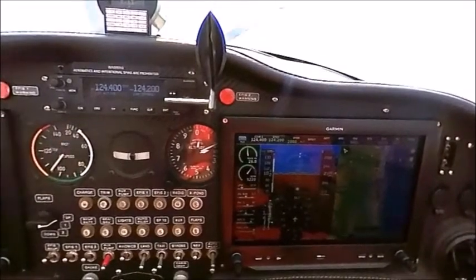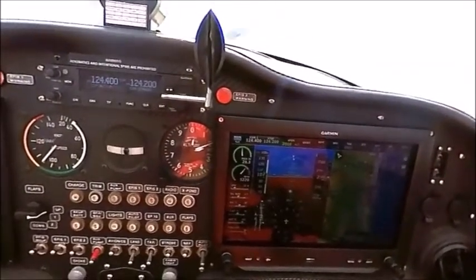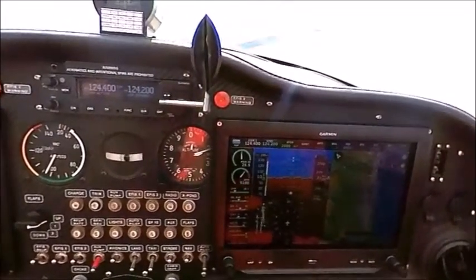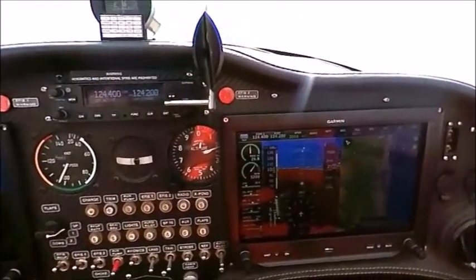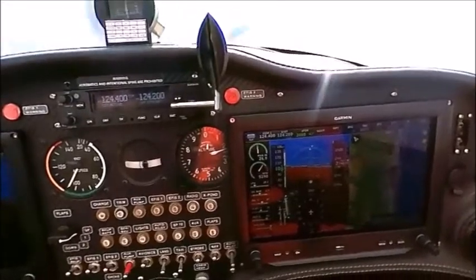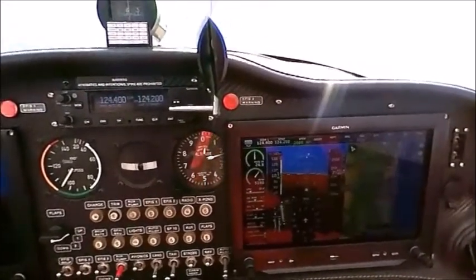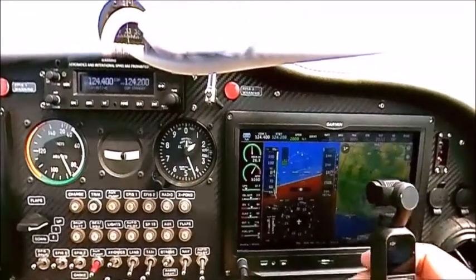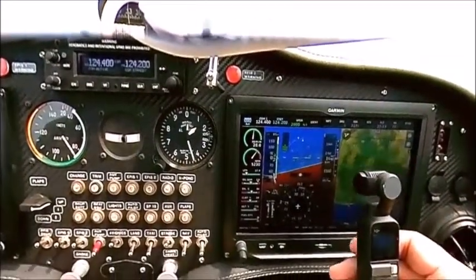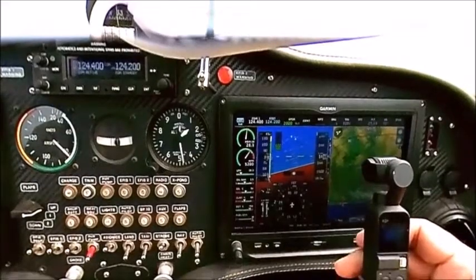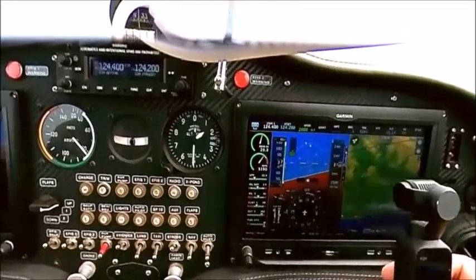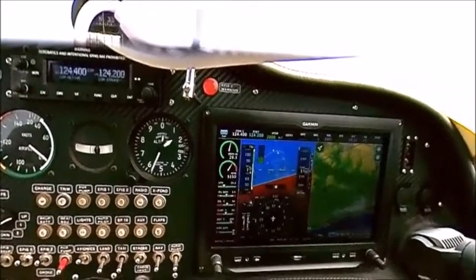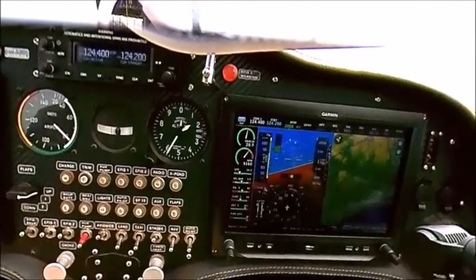Okay, so I'm going to be doing some examples. I'm showing you different air speeds. You will see over here with the analog system, it will show you we're going about 105 knots, while on a digital system, you will see that we're going at around 100 knots. So there's a difference that we are able to see over there. You also will notice that with the vertical speed indicator, there would be a bit of a delay, which one needs to take into account while flying.